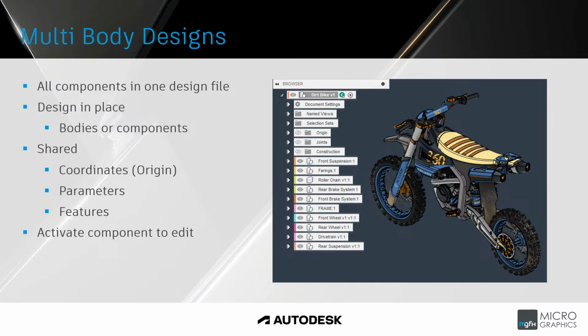So with multi-body design, you've got all of the components within one design file. The drawback to this is that only one person can edit that file at a time. If I have that dirt bike assembly open, I'm the only person that can work on it. If somebody else needs to work on it, maybe they're doing design work on the covers for the exhausts while I'm doing design work on the front fairing, I would have to click save and exit, and then they would be able to open the file and do the work that they need to do. So when it comes to working in teams, that does have a drawback with the multi-body design process.